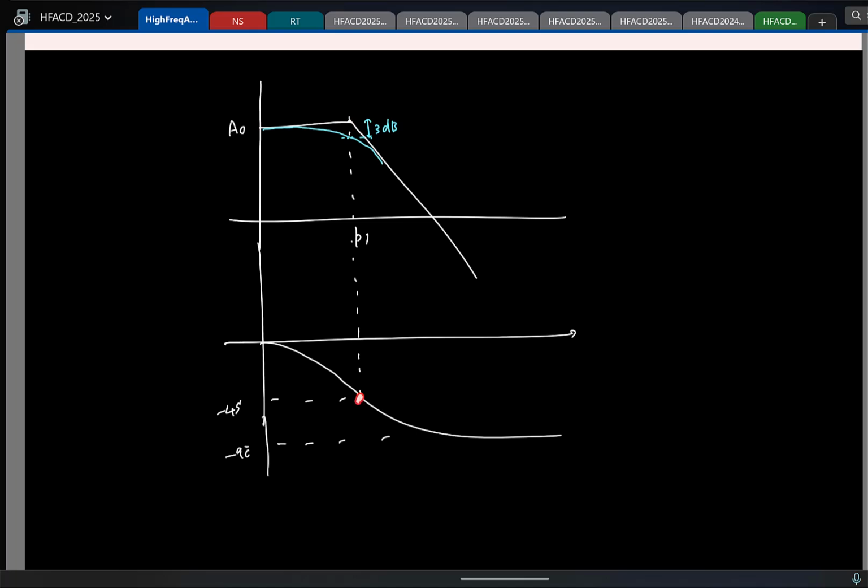Whereas you see the phase, you would have incurred significant phase drop. So which means you can get more information about whether you have poles or 0 around a particular frequency if you actually look at the phase plot than the magnitude plot. So just don't look at only the magnitude and make any conclusion. That's the bottom line.